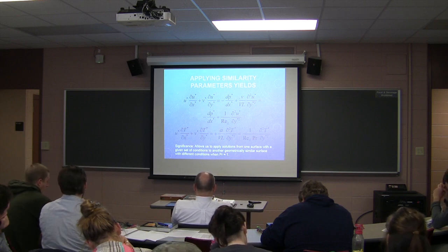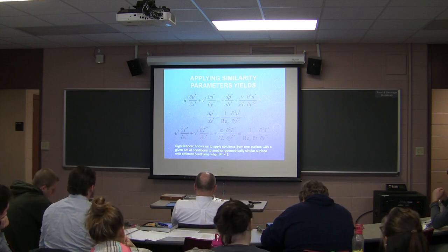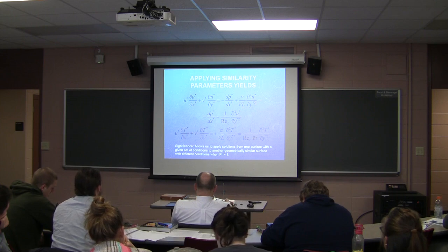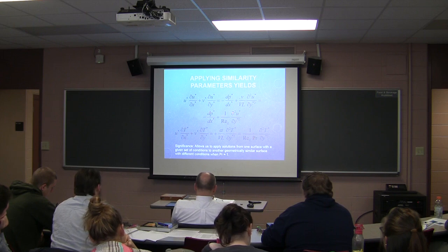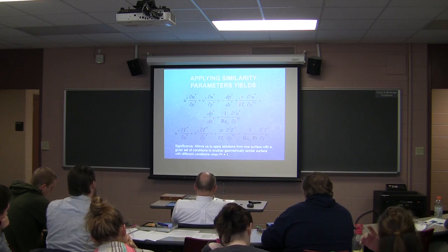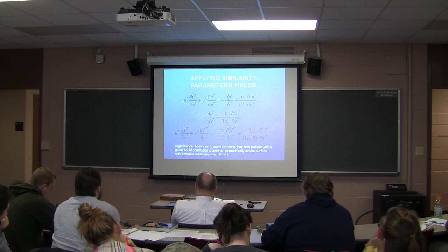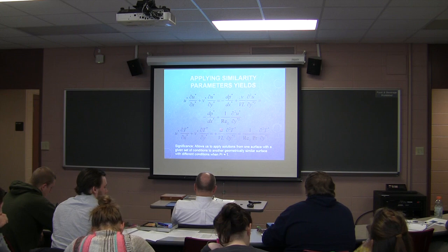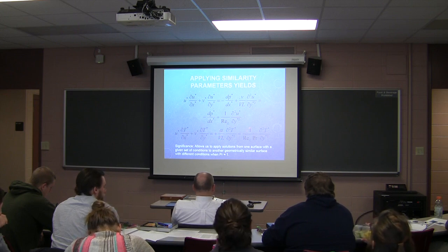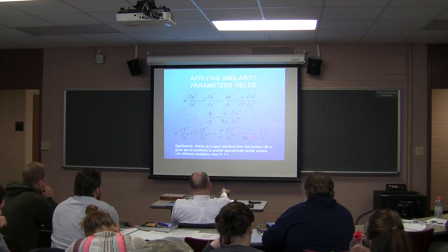Here you have the momentum terms. You have the pressure and the shear stress terms. And it turns out that this term comes down to here, but the nu divided by V over L is the same as 1 over the Reynolds number. Down here for the energy terms, we end up with this result, and that is 1 over the Reynolds number times the Prandtl number.